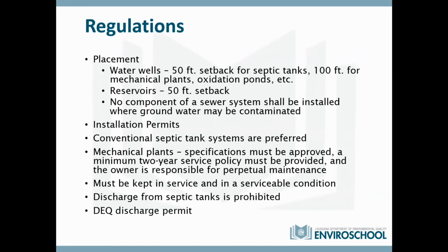As far as placement and some general regulations, this slide is from a presentation I did to a bunch of water operators. So I was taking it from a public water system standpoint, which is why I included these things, but it's interesting for everybody to know. When it comes to water wells, there are setbacks for septic tanks, mechanical plants, and oxidation ponds, and also for reservoirs, and basically any component of a sewage system. Basically, we want our sewage system to be away from our source of drinking water. You have to get installation permits from the Department of Health.